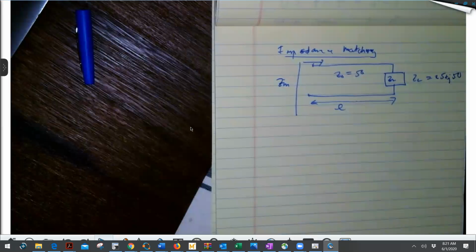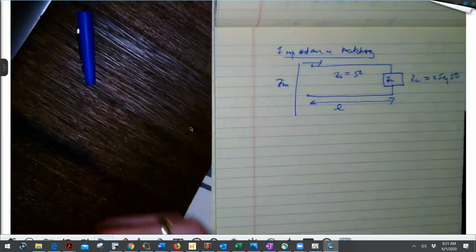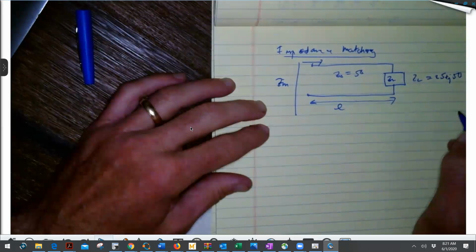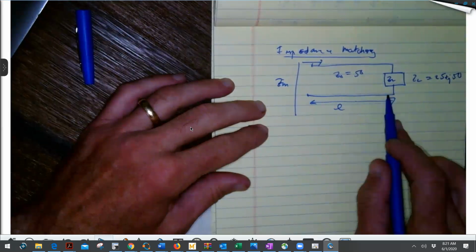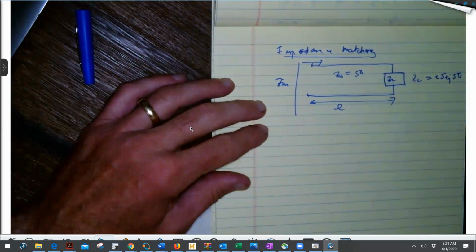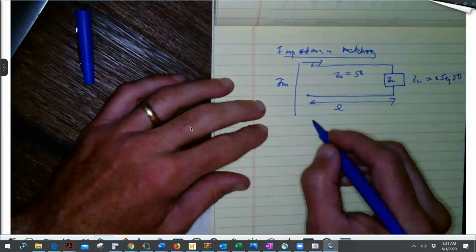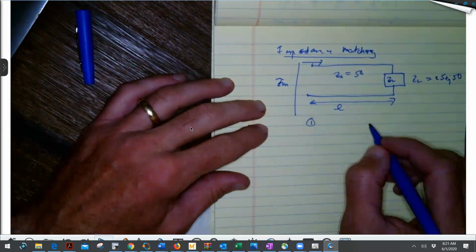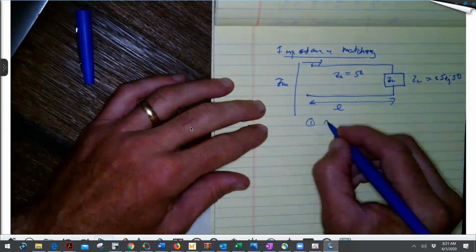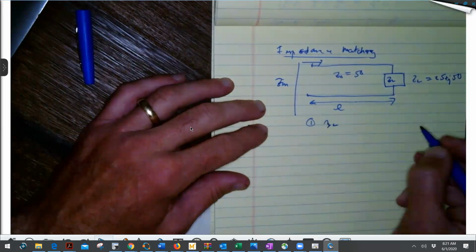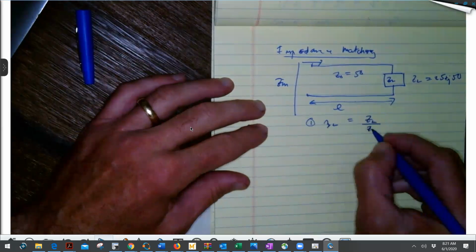And this is an arbitrary value. So if you're using a Smith chart to find the input impedance, or basically the impedance of the line at any point, at any distance L away, your first step is what? Can anybody tell me? This is from Friday. We normalize the impedance, right? Whatever the load impedance is, we divide that by Z naught. Correct, class?